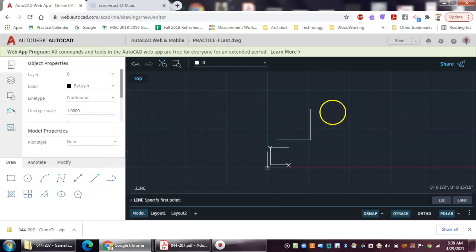So now if I go to draw my line, I'm going to come right up to this endpoint. Notice as I draw, now it's going to key in. See how you get that green dotted line at 45. So using polar helps you quickly add lines at different common angles that we use all the time. And you'll notice in terms of the direction of these polar lines, generally AutoCAD goes from right, shooting around to left. So if you're entering some angles, it's all referenced from the positive X direction and moving around as you go. So that's the polar coordinate.